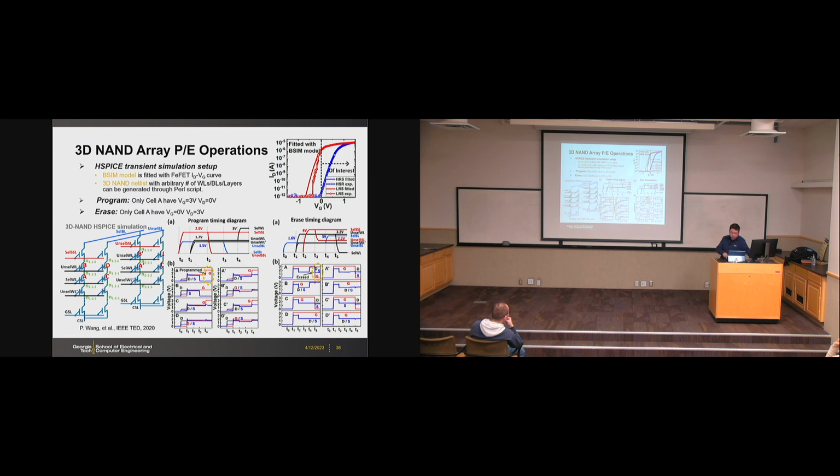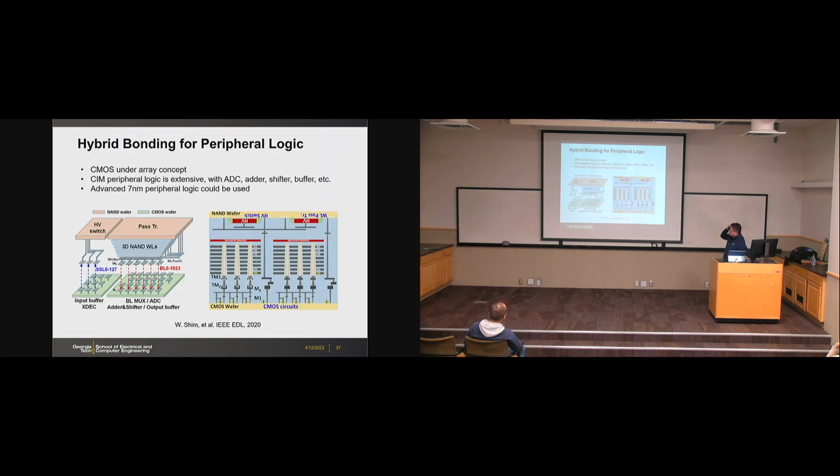And this has also become attractive to the industry. For example, recently Samsung asked me, can we do some initial study to evaluate the ferroelectric for the 3D NAND configuration. But I think the ultimate vision for this one is to have heterogeneous integration, because the 3D NAND process still has the peripheral circuit in some older CMOS technology node. It's not very powerful.